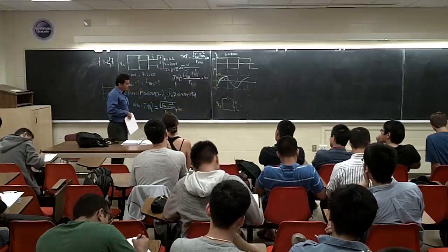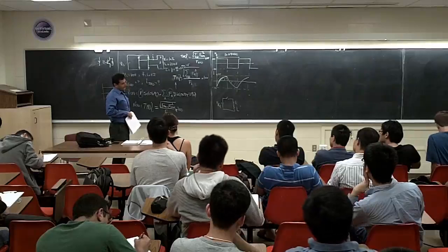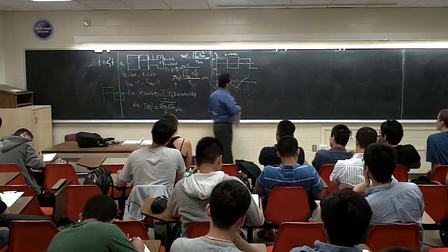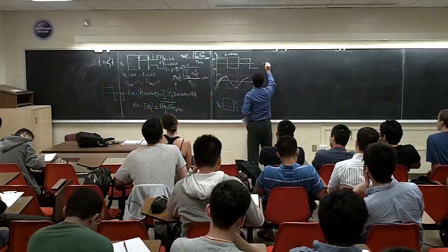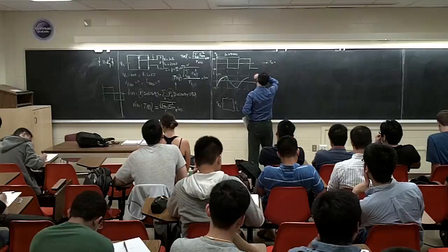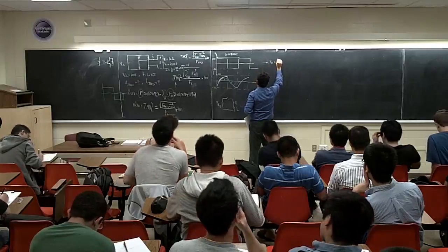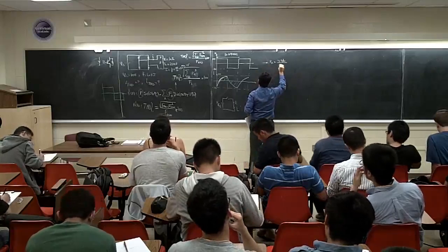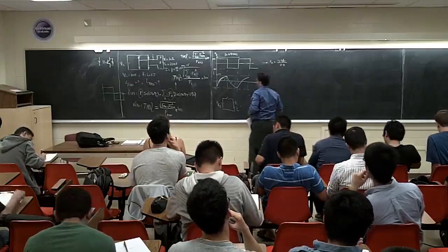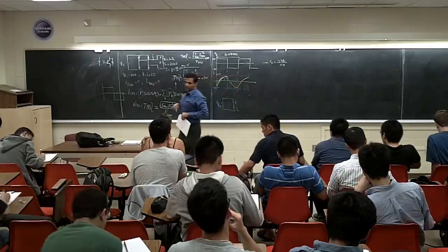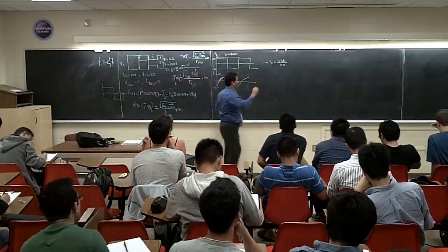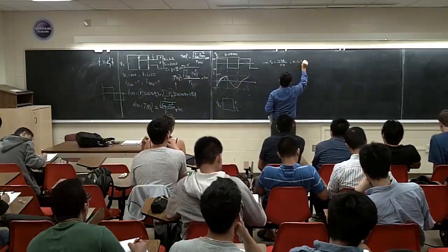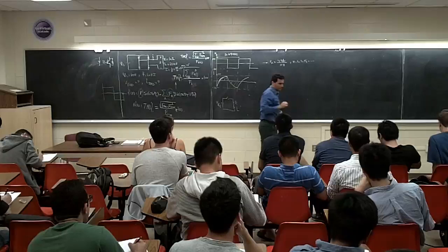Now we need to calculate. We know the Fourier series for this waveform. What was that? We said Vn is going to be, I think, 4 VDC over n pi, and it has only the odd harmonics: n equals 1, 3, 5, and so on.